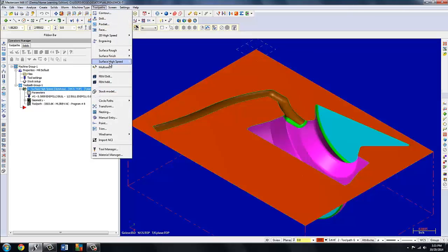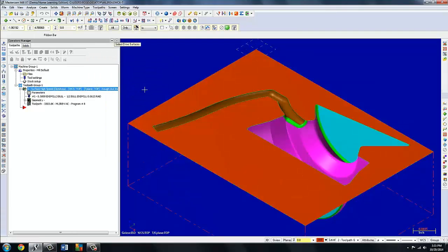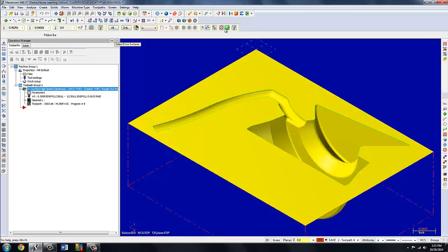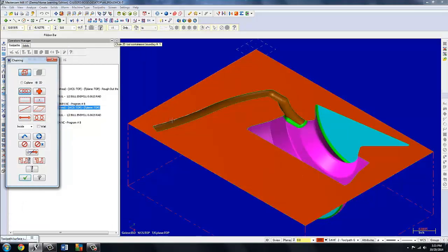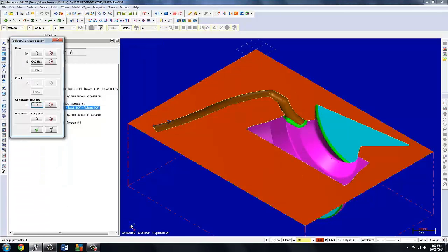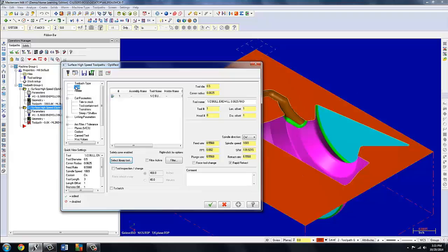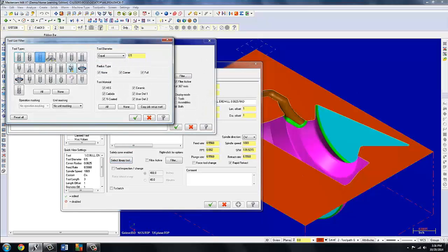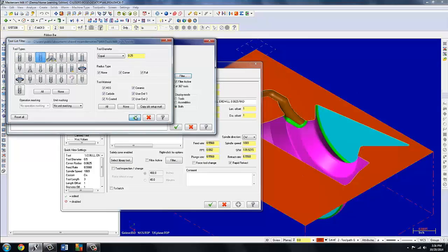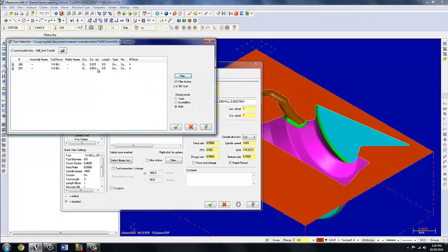Toolpaths, surface high speed, OptiRest. OK. Again, quick mask, end selection or enter. Containment boundary will be the silhouette. We'll pick that. Check out. OptiRest. The tool is a 1/4 inch bowl with a 0.0625 radius. Select a library tool. The bowls are on. I just put a 1/4. Check through the bowls. I need the 0.0625 radius, which is this one. It's just rounded.